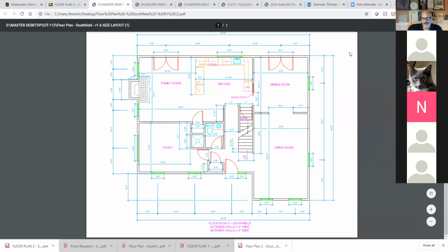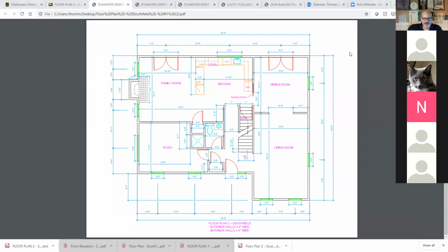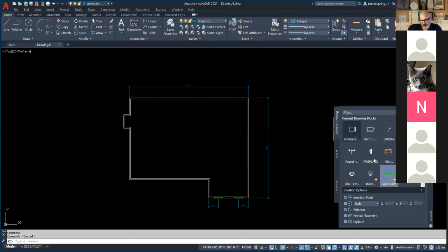So we'll go back to here. And I'm just showing these different tools. There's a lot of different ways to do this. I'm just walking you through this so that you guys can mature on this. So I'm gonna go here. Same thing I did before. Let me make my layer current though. I'll make Windows my current layer. Click here. And I'm gonna go ahead and touch it here. I'm gonna slide it down. And as I slide it down to here, I wanna go 22 feet 6 in my enter key. Boom, it does that.